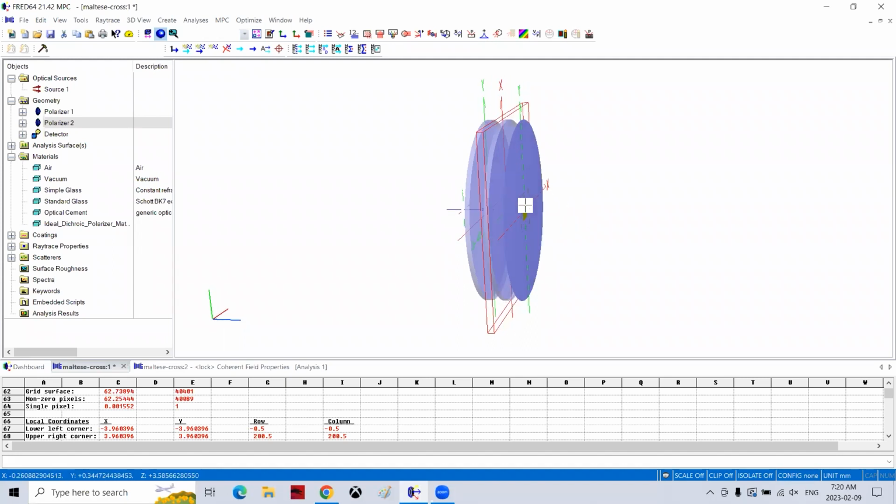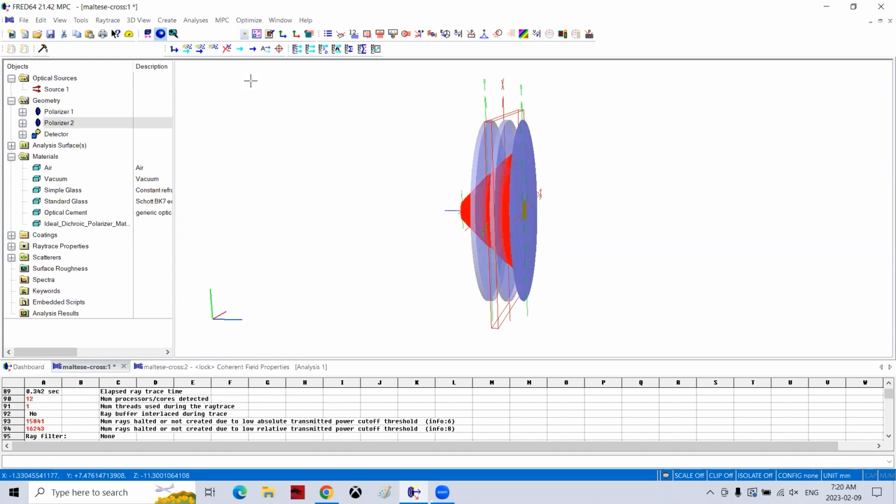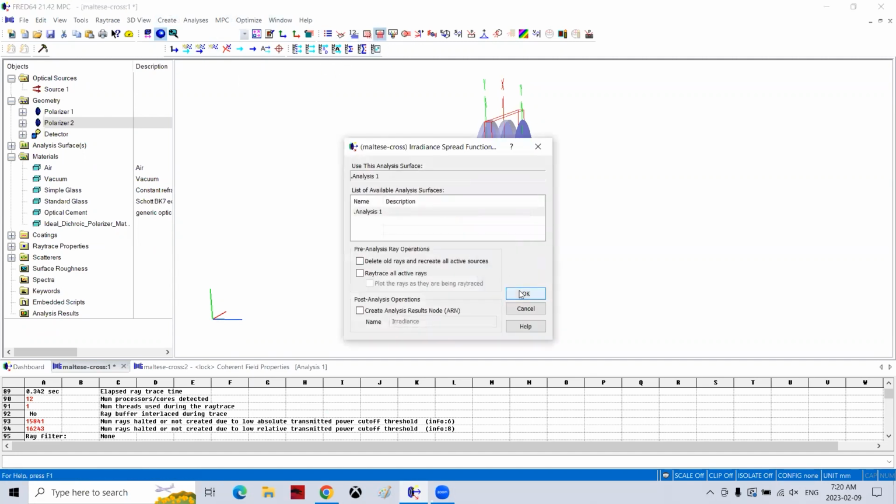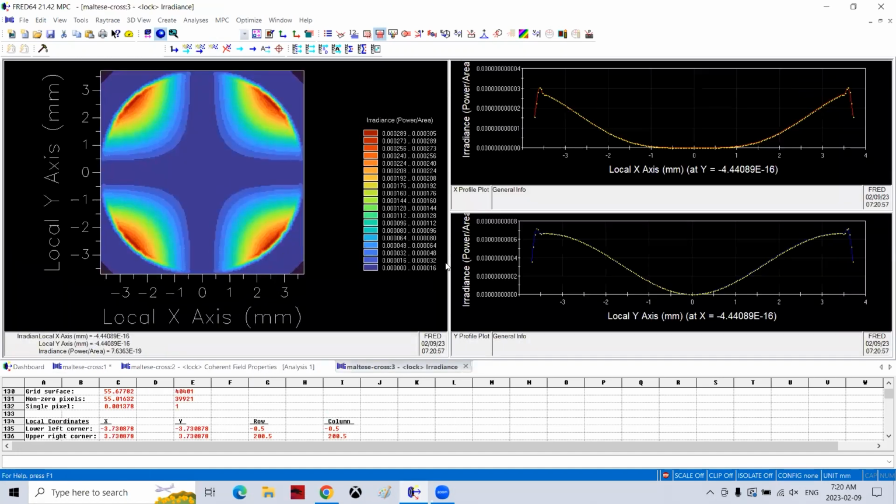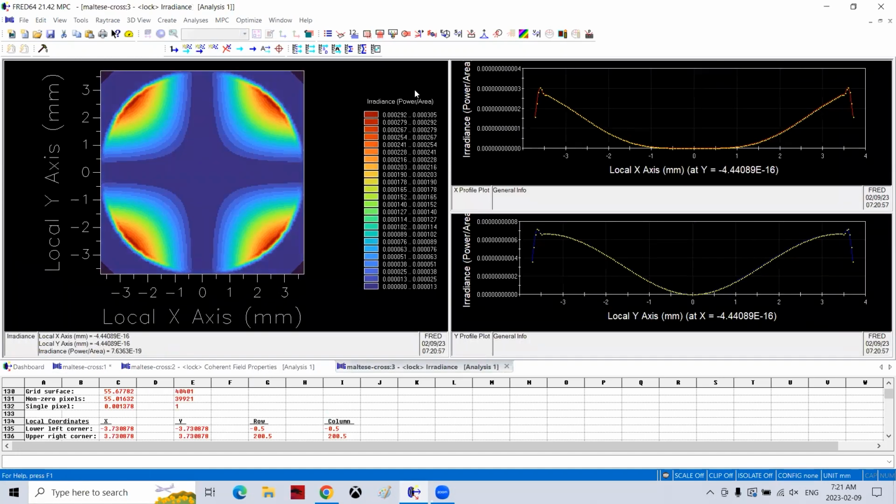And what we're left with at the end is essentially what's called the Maltese cross image, which I'll show you. I'll show you first of all just in the irradiance. Quite simply, just a small amount of power left over, and this sort of cross picture in the center here is something that can be used to help diagnose the birefringent materials we're using or things like that. So this is the Maltese cross. Just these small components here don't get filtered out by the cross polarizers.